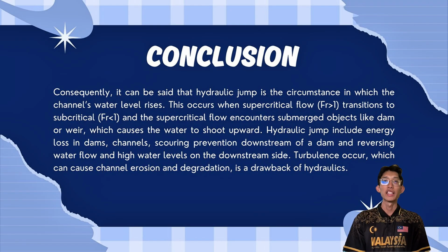Hydraulic jump applications include energy loss in dams and channels, scouring prevention downstream of a dam, and reversing water flow and high water levels on the downstream side. Turbulence occurs, which can cause channel erosion and degradation, and is a drawback of hydraulic jump.